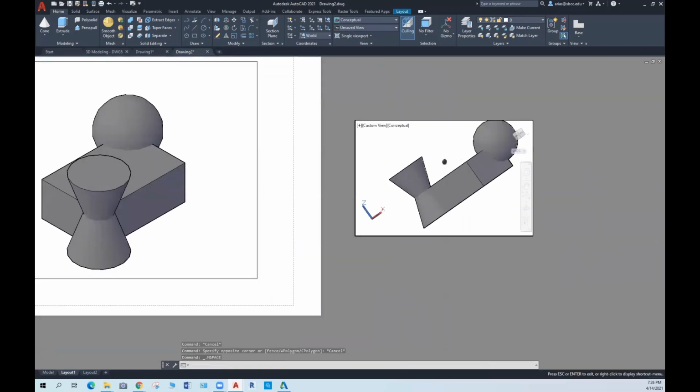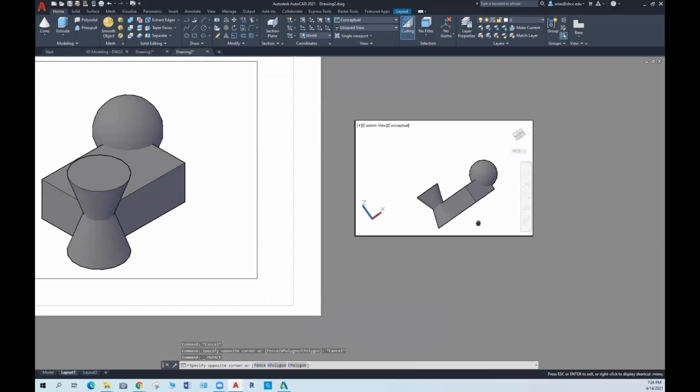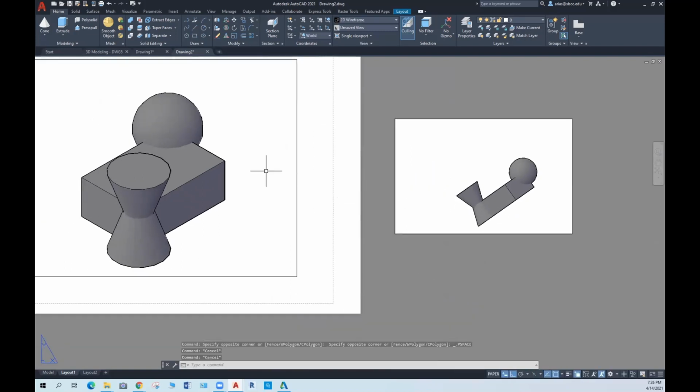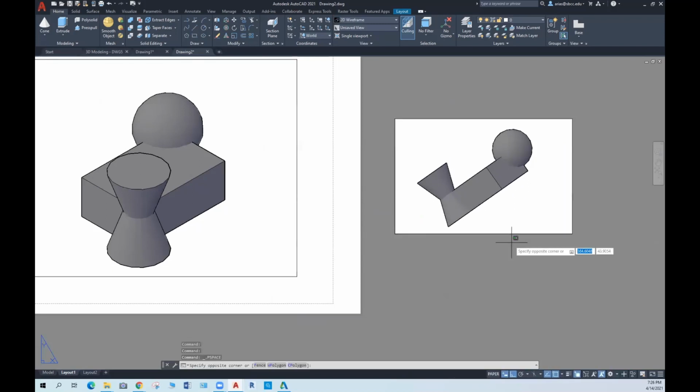So see, I just created this view. This view is an orthographic projection of this object seen from here, right? And so that's what the computer created. And this is a solve view. It's called right side. Now let's look at the layers so that you can notice something that's happening.